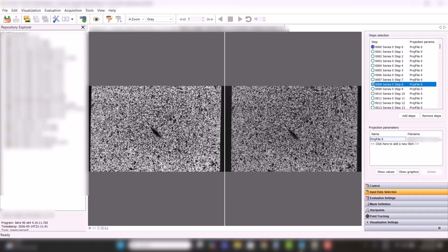From a fundamental DIC standpoint, where you'll theoretically always have a high quality speckle pattern from start to finish, large differences are going to come from large deformations and/or rigid body motions. But from a practical standpoint, differences in images could come from lighting changes, speckle pattern breakdown, etc. And so that's the purpose of rung steps: they aid the DIC algorithm when the specimen and the corresponding speckle pattern have deviated significantly for whatever reason from the reference step. Rung steps help the DIC algorithm bridge that gap.